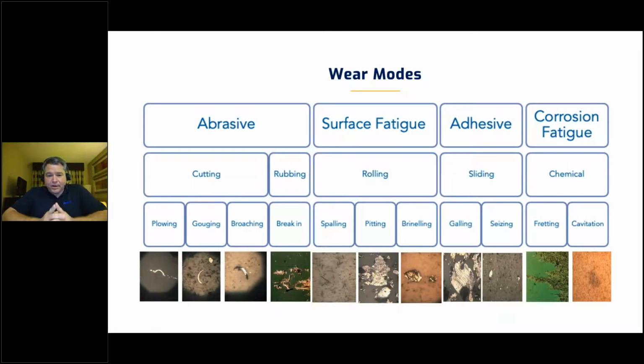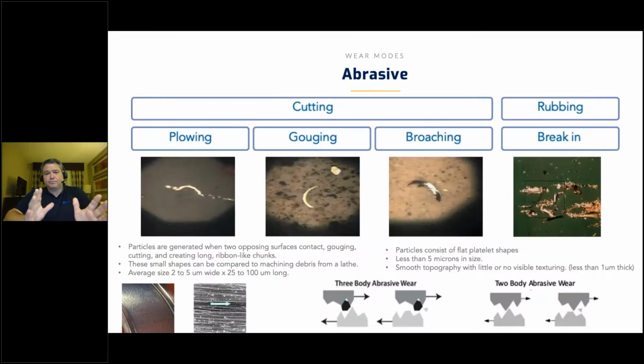So it's a very scientific process. You can see, this is a general classification: erosion, corrosion, fatigue, overload, adhesion, surface fatigue. All of those show up as different shapes. And so the next couple of slides, we're just going to zoom in on that and just talk a little bit on a high level about what that looks like. Because we can take an oil sample and we can look under magnification. Again, there's technology out there where not only are you using laser to count the particles, but they can use lasers now to not only count, but to determine the shapes.